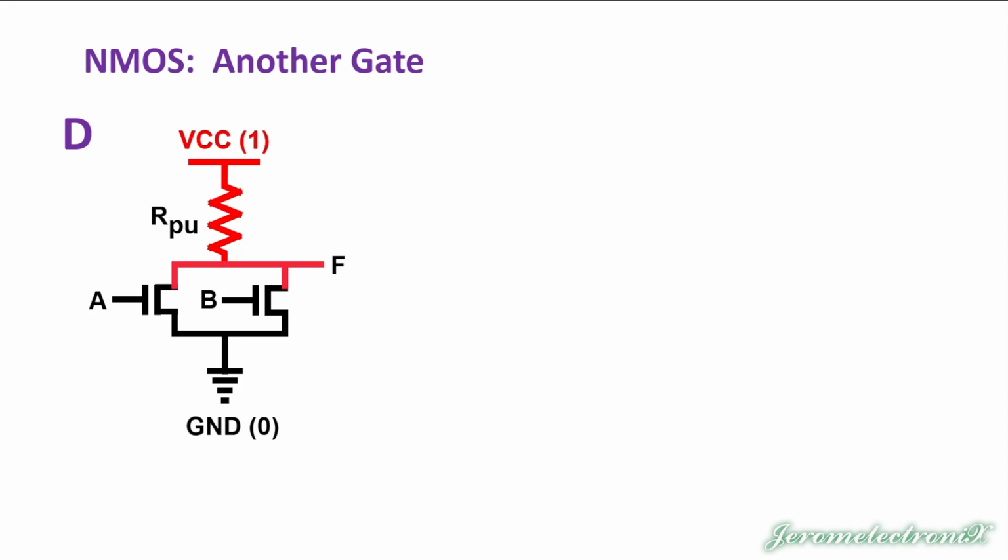So it could go through transistor A, or, I focused on or there, or it could go through transistor B, or it could go through both. Okay, so we know that this is going to be a member of the OR family, whether it is an OR, a NOR, an XOR, or an XNOR, but it is a member of the OR family because you can see that by the pattern of the configuration.